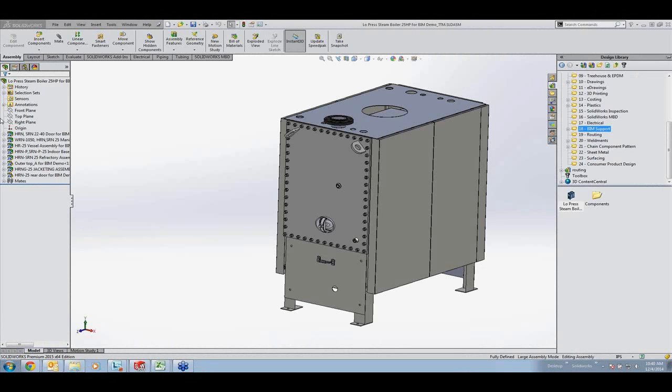I can also use this to split the surface, just like I could in the past. So trim surface with this sketch entity here. I'm going to keep the selection of the inside or the outside here and accept that.